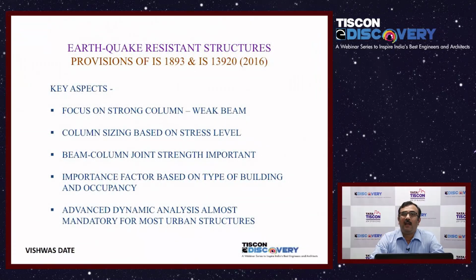And very importantly, they have now sort of made mandatory the use of advanced analysis engines. Why is that? Because when the earlier codes were established, there was hardly any penetration of computers as well as software. Today we can't say that. Today practically everybody uses computers, everybody uses tools. So whether it's a village or a city, engineers have the benefit of using those tools, and we should make use of them. That's why they are making you use dynamic analysis, which gives us a better understanding of our building's behavior during an earthquake.